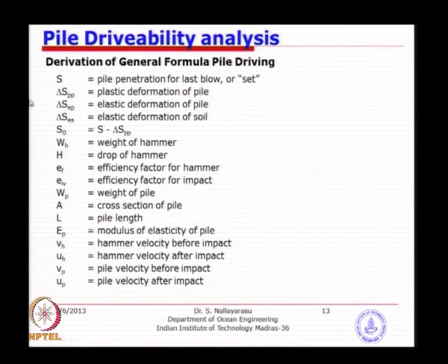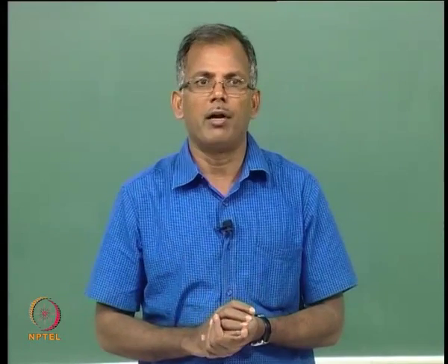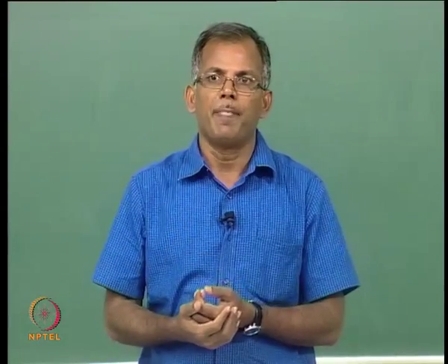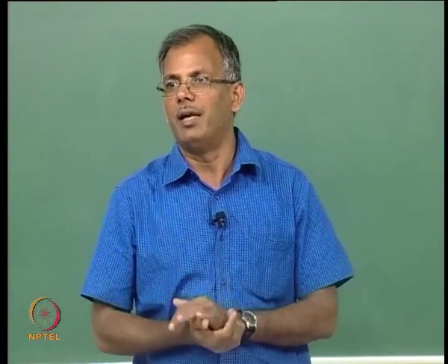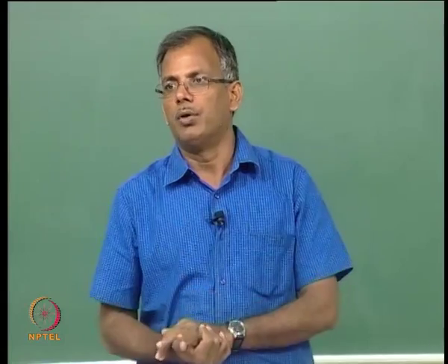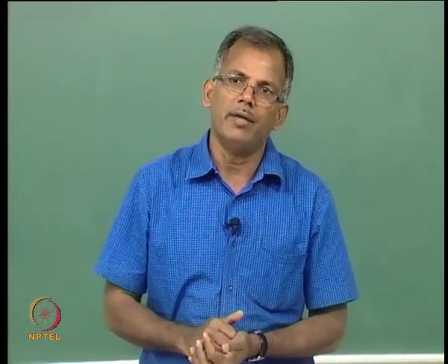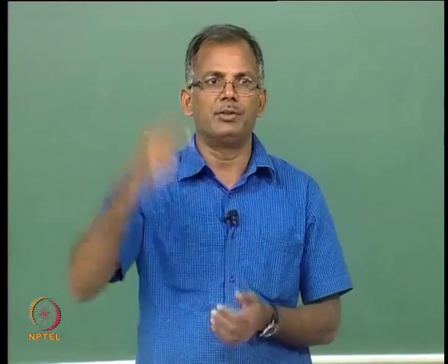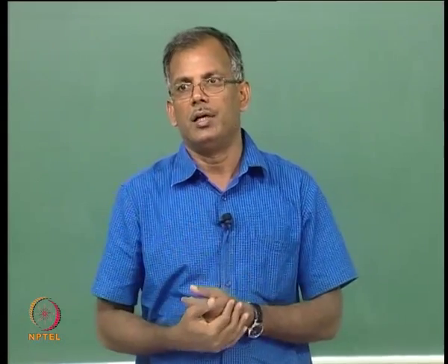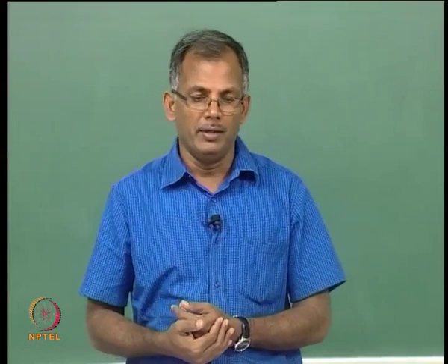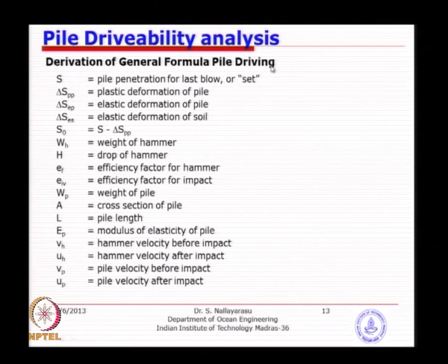So, S is the pile penetration, or we call it set, sometimes the notation, per each blow, or it could be consecutive several blows. In reality, we normally use 300 blows as a reference. If you look at offshore pile driving, we do not look at actually every blow, what is the set value. For a consecutive, say, 300 blows, you just keep on driving and then find out what was the previous 300 and the current set value or the displacement of the pile, and that we call it set.